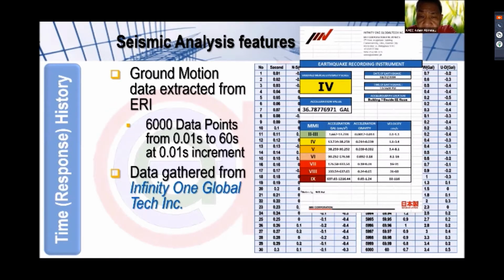So the acceleration value is recorded as 36.8 gals, and divided by 981, that will give you about 0.036 g.